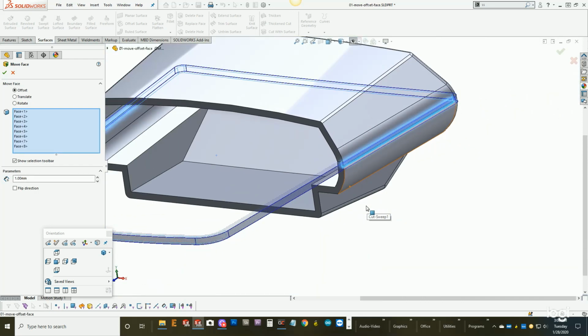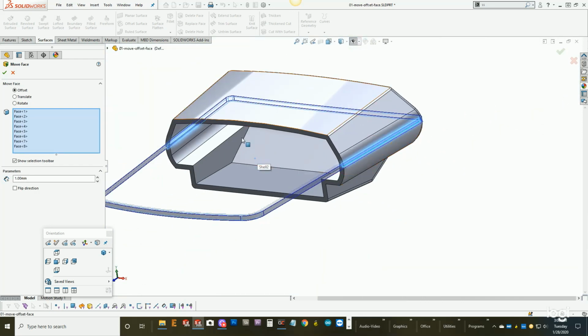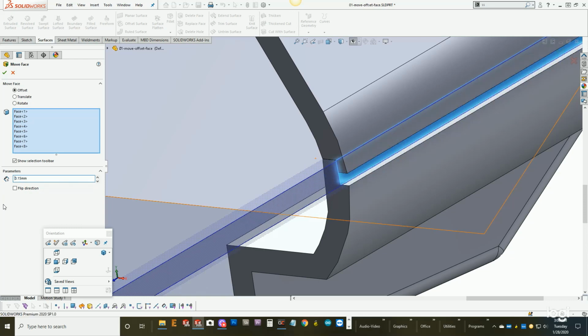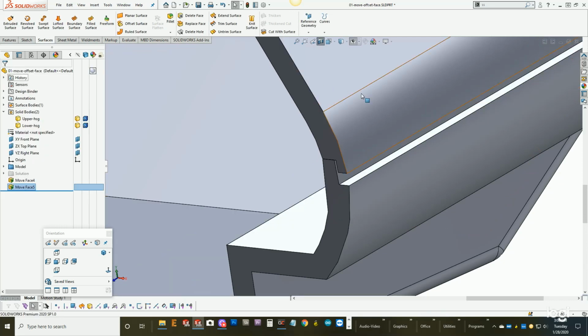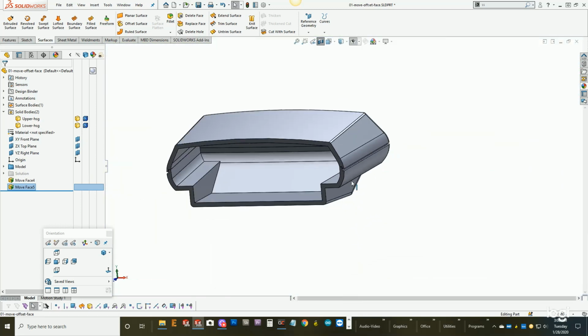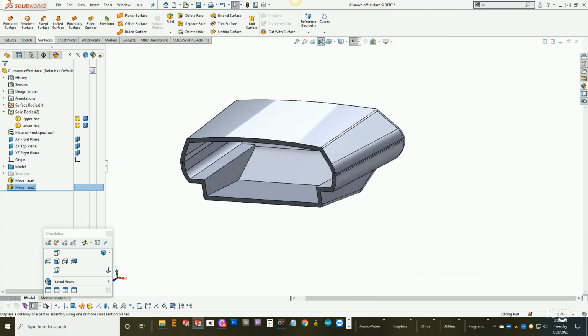And what it's done is, even though I have it in section view, I can see it's picked that entire surround. So now I'm going to enter my tolerance, which I think 0.15 should be a good number. I'm going to reverse it again because I want to take away that wall material. And now I have that tolerance gap. And I've been able to do that rather quickly.